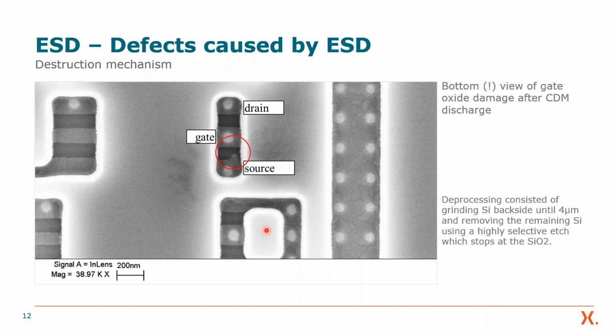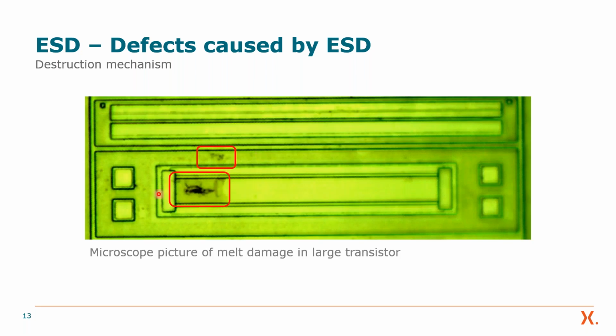Okay, if you open up an IC and want to understand how it was destroyed, it's very often not possible, and sometimes you find some hints, like here, for example, this burn mark near the source, which indicates that the gate probably had a problem there. And this is something which is really obvious, EOS. This trace inside the transistor just melted because of a too high current density.